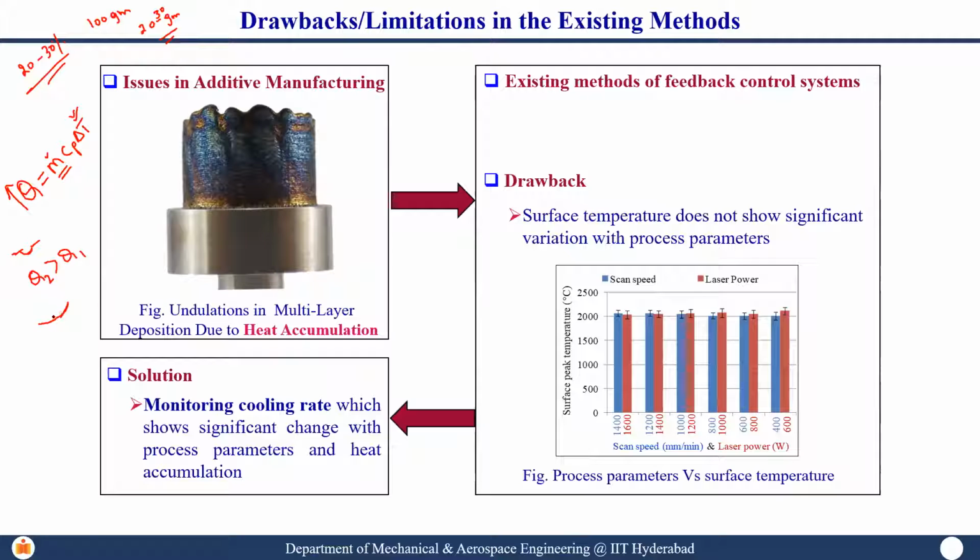The moment the molten pool size increases, you understand that our spot diameter is only 2.2 mm, whereas my powder footprint diameter is 5 mm. So more powder comes into the picture, catchment efficiency goes up, which essentially means delta T is not going up. Your m is going up, which once again means you will not observe any change in the temperature.